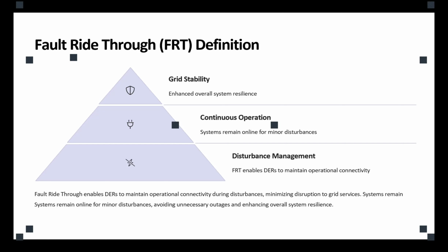Basically every year, when we have a wildfire in California, this thing happens. The inverter would trip because the wildfire would disturb some of the transmission lines. There is going to be a short circuit, and the inverter would detect that fault and immediately disconnect from the grid. So now the generation and demand balance is disturbed.